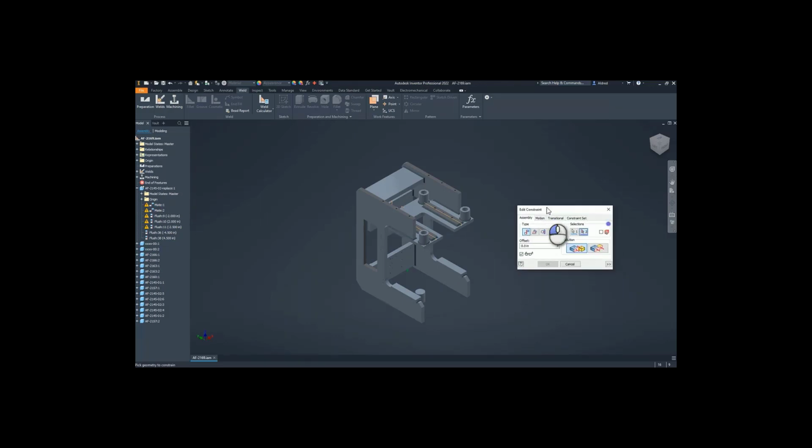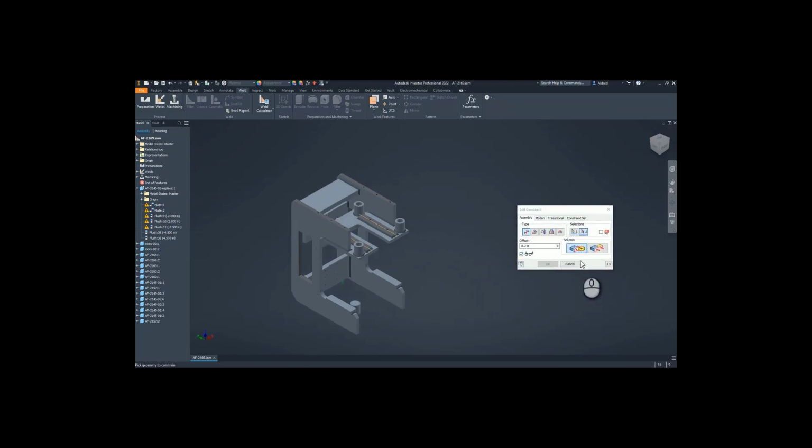But as you can see, I have created this replace component over here instead of the normal AF-2145-02. Now, yes, you might say, well, it didn't really work because of the constraints that came up, which are now sick. But this does happen when you do your normal replace as well. So it is normal functionality in Inventor, but this is just one of the ways it allows you to replace components that are sitting in sub-assemblies as well with the use of the Vault.